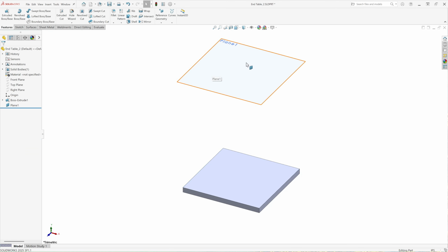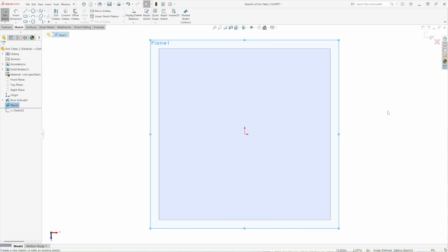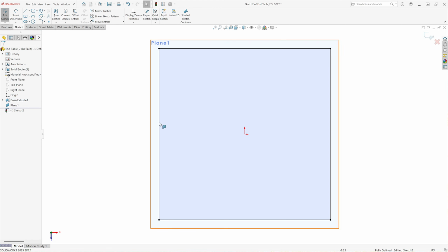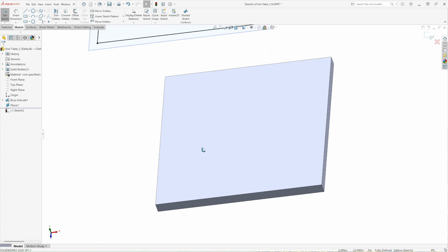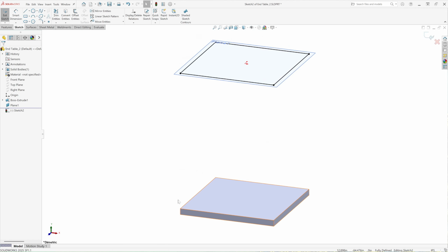I'm going to select the plane 1 I created. Select it. Sketch on it. I'm going to click on the extruded square earlier, right here, the face. And I'm going to go convert entities, so I don't have to draw that again. Just to show you, it took that and converted it up into the plane. Same, 16 by 16 inch square.